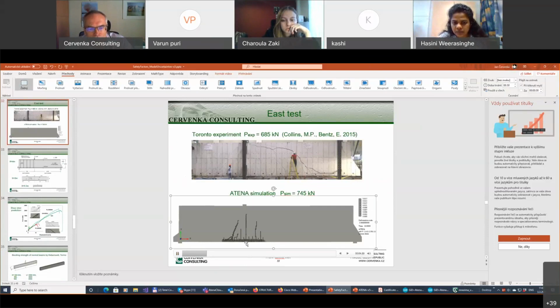These cracks are spreading. You also nicely see that at the bottom there is reinforcement, quite heavy reinforcement. So we have a lot of fine cracks around the reinforcement, and these fine cracks at some point coalesce into one major bending crack propagating through the height of the beam.